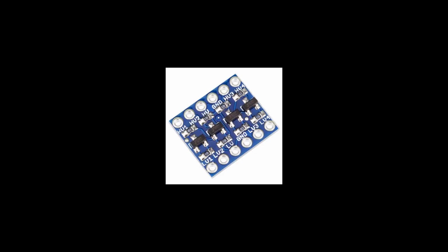Another component in our project is the 5 volt to 3.3 volt logic level converter. The Raspberry Pi GPIO pins work with 3.3 volt logic levels and are not 5 volt tolerant. If you apply 5 volt to a GPIO pin, you risk permanently damaging it. However, you can easily use 5 volt sensors or modules if you convert their 5 volt outputs to 3.3 volt using a level shifter. This ensures the GPIO pins on the Pi only see a maximum of 3.3 volt.